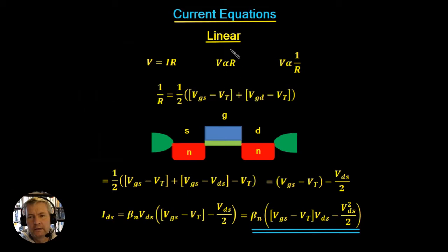But we're not interested in the resistance, we're interested in the conductance. That is how easily the charge is going to be conducted across the layer. Now the conductance is given by 1 upon the resistance. If the volt drop across the layer increases, it must mean that the resistance has gone up, so the conductance, the ease at which the current flows, must have gone down.